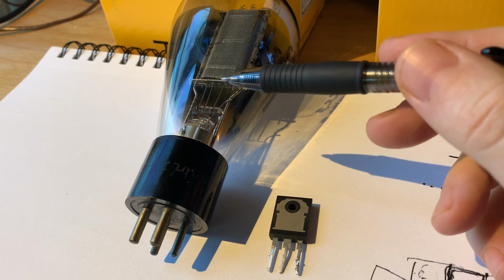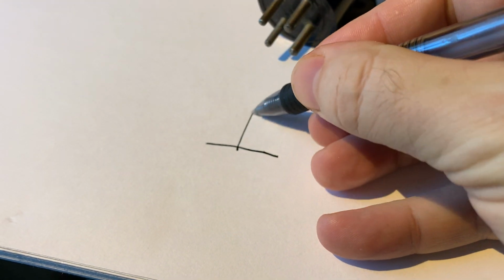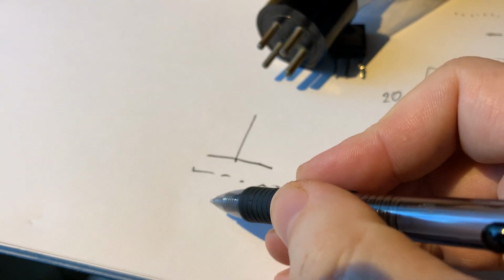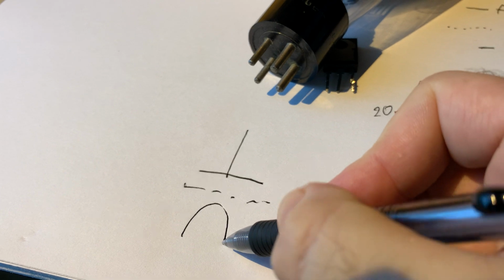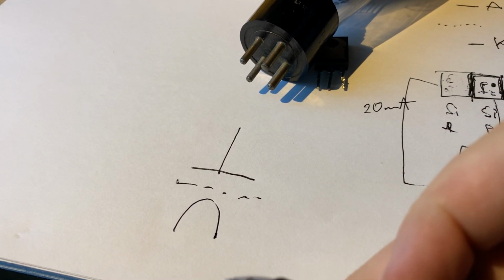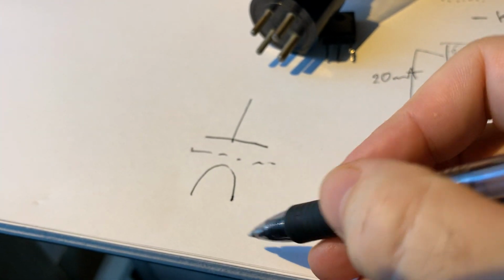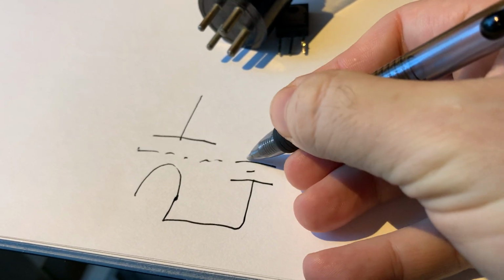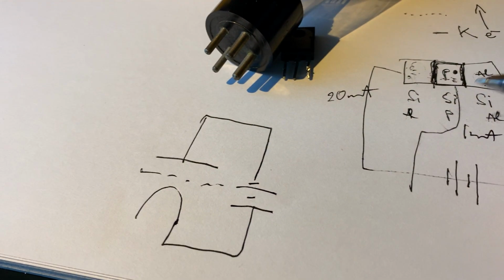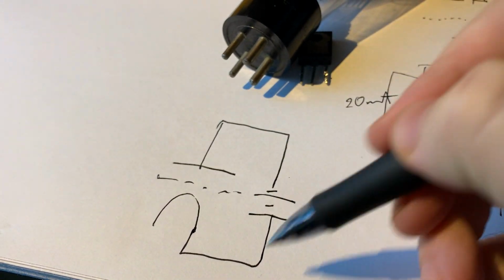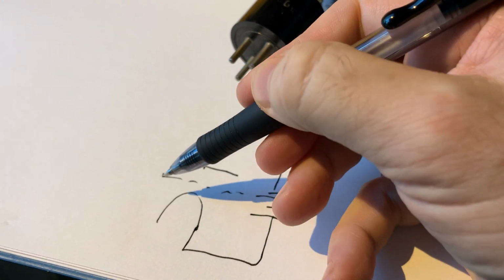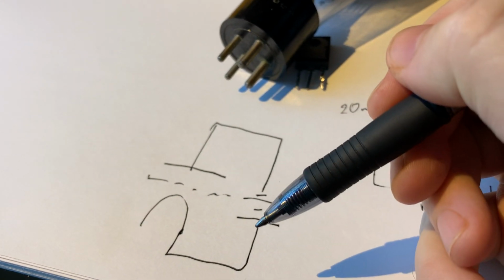In the vacuum tube, you do not have that situation. Let's say this is our anode, and that's the control element, which is called the grid. And then we have the cathode, and in the case of directly heated tubes, they draw it like a U shape. If you put this into a circuit with a battery, closing the circuit, there is current flowing through here. However, if we apply negative voltage to the grid, then we shut down the flow of the current.